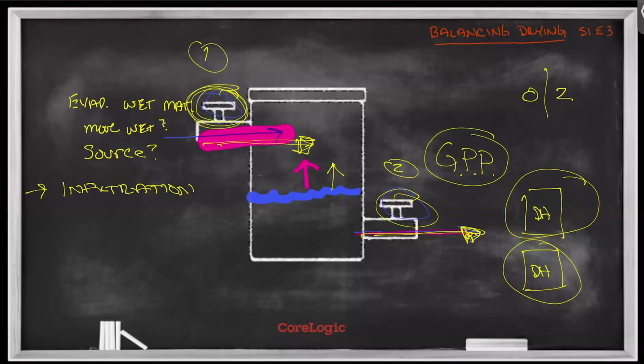They're not trying to hear all the drying equipment in the background. Maybe it's not the property owner, maybe it's just property occupants, right? And when you get back to do your monitoring, miraculously the dehumidifier is running again. You take your readings, humidity is increasing in the environment. You think, I didn't install enough dehumidifiers, so you put in a second one. All you really did was give them another power button to hit when you leave, right?